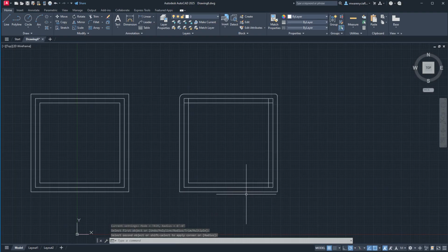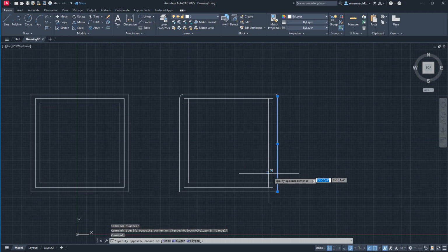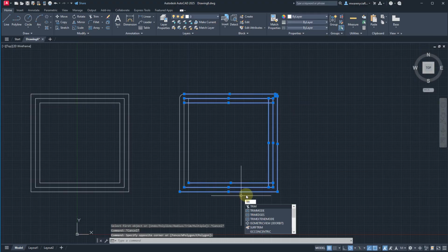All right. The trim tool works in a sort of similar way. To use the trim tool, there's a lot of things here where I'll recommend you guys select what you want to do and then start the tool. And trim tool is one of them. I suggest you do that because often it's easier than starting the tool and then trying to make your selection, and then, I did it wrong, and having to escape out and you lose your selection. I find it's easier just to do the selection and then start the tool.